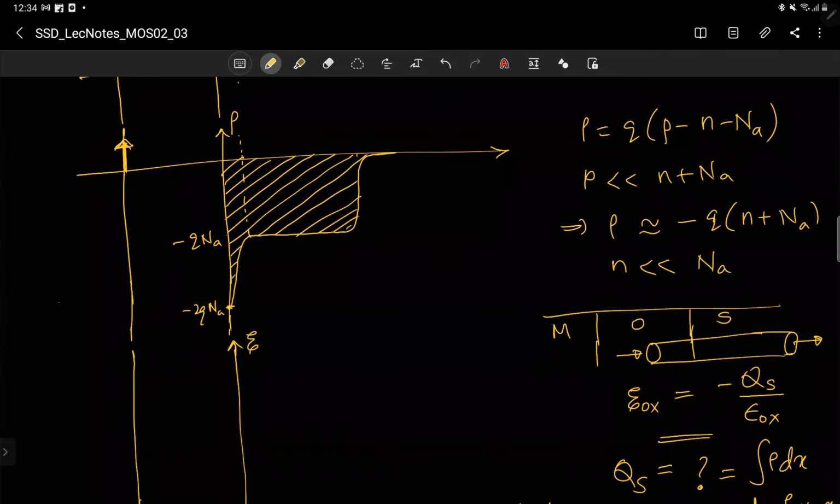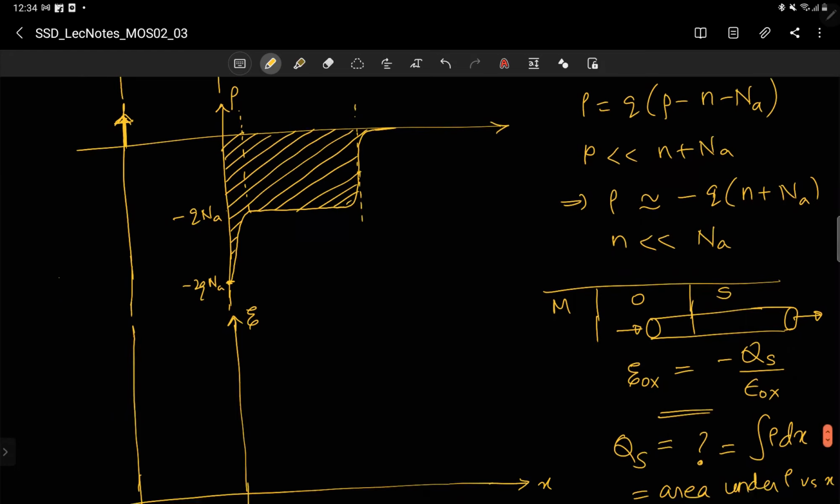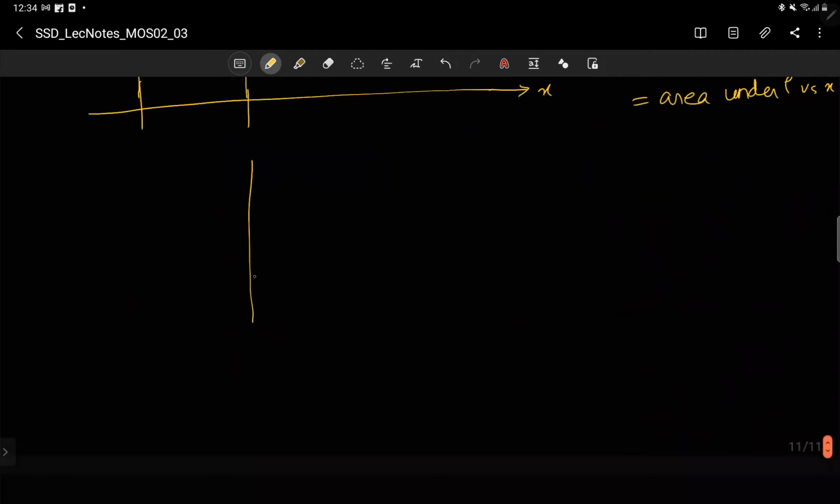Here is where we make some approximation. The first approximation is the depletion approximation. That is like making this really sharp, because it is transitioning slowly. So let us make this sharp. I will plot rho here for the approximation. Actually, I should not say rho approximation.